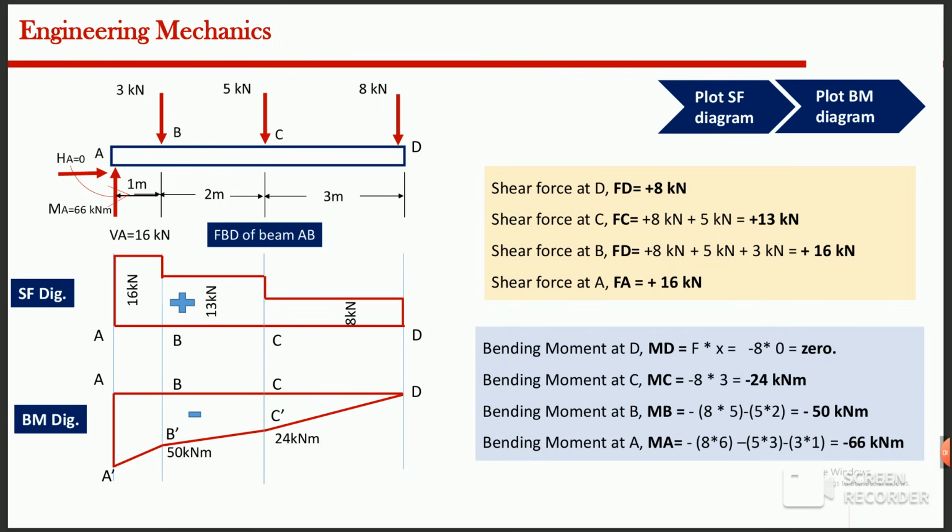Let us summarize today's lecture. We learned the definitions of shear force and bending moment. We studied the sign conventions used for both quantities. Then we followed a systematic procedure: drawing the isolated beam, preparing the free body diagram, calculating the support reactions, determining shear force and bending moment values, and finally plotting the shear force diagram and bending moment diagram.